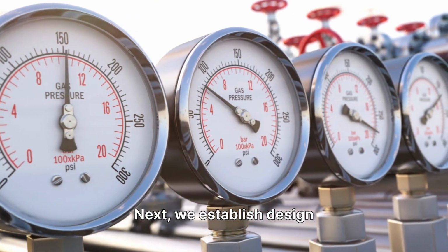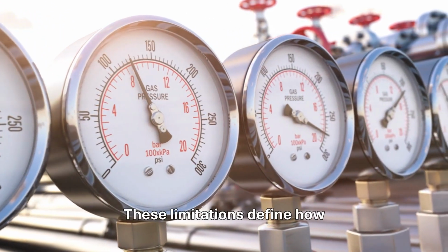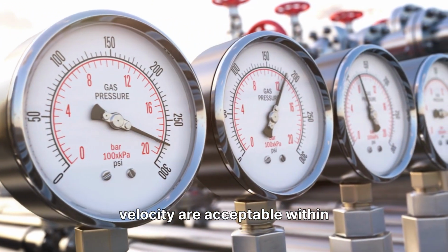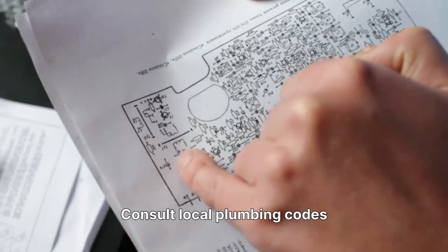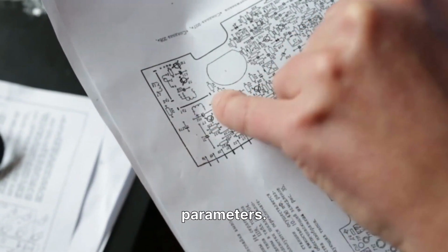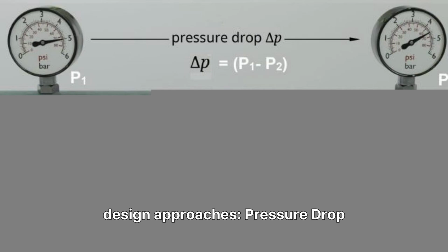Next, we establish design limitations for the system. These limitations define how much pressure drop and velocity are acceptable within the piping network. Consult local plumbing codes and apply sound engineering judgment to set these parameters. Here are 3 common design approaches.